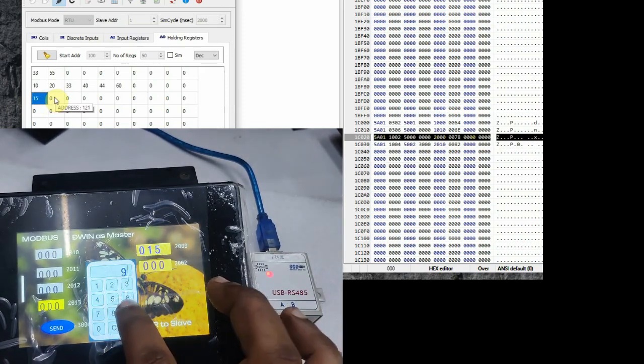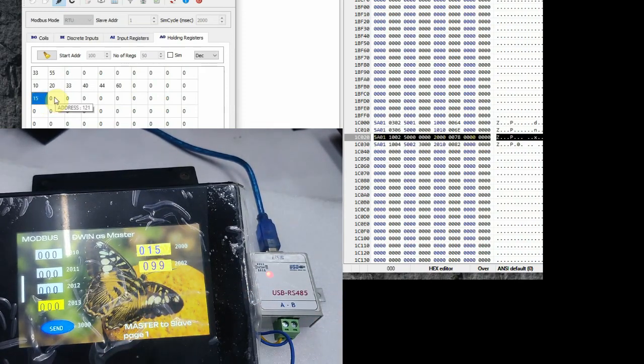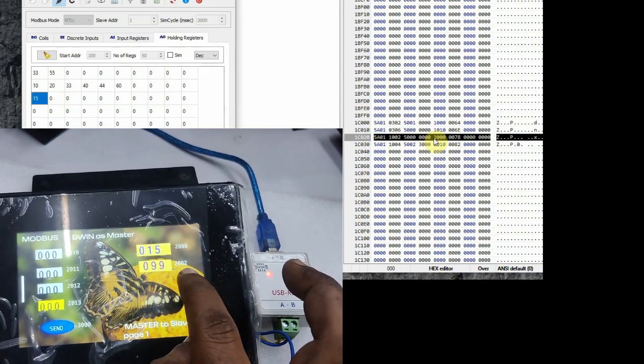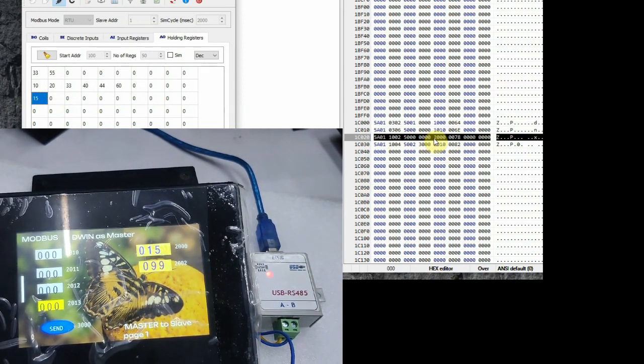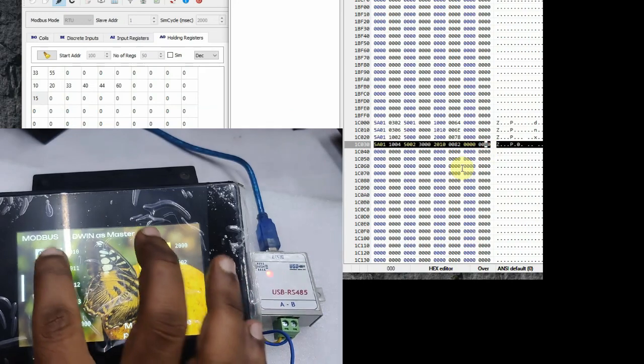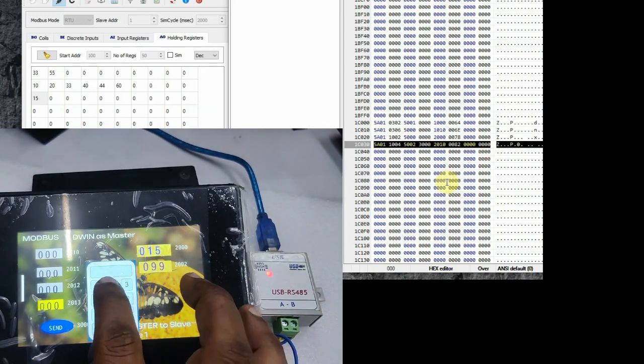And finally the 1C030 instruction, we use the command 10, operating length is 4 words, and mode is 02 here, so it looks for 5A lower byte at VP 3000, and if it is okay, it transfers data starting from 2010 to the slave starting location 1300, which is the fourth row of the slave. 1300 is decimal, which is 0x62.